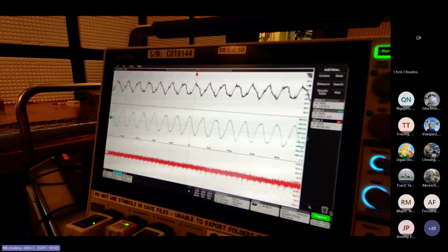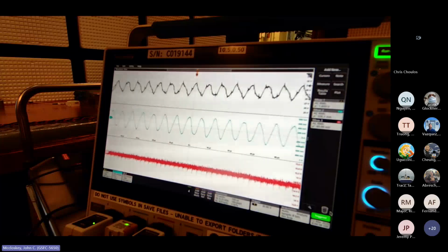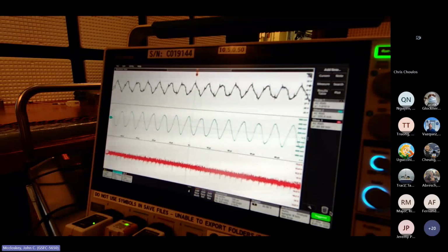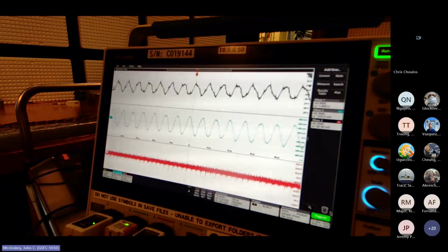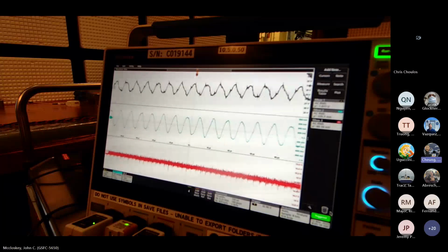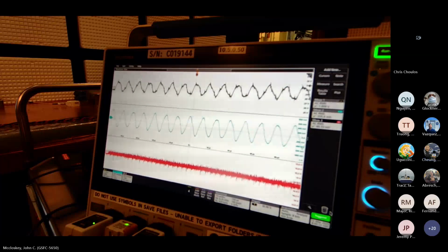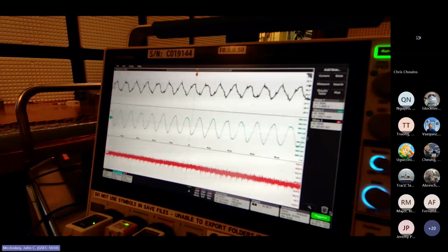Yeah, we can go back to 30 hertz, because I think we were seeing a pretty significant amount of the 30 hertz coming through. Here at 150 kilohertz, we're not seeing much of the 150 kilohertz injected signal coming through. This is just the noise of the converter. And what this is, pretty much, is what we see above about a kilohertz. That's actually more than the feed through of the 30 hertz, which is 160 millivolts. Yeah, we'll just go back to 30 hertz.